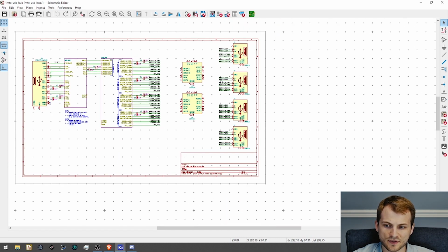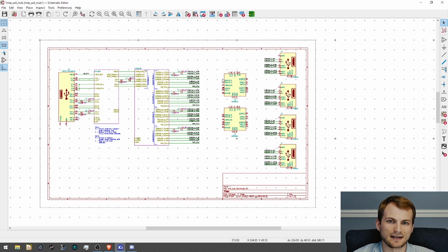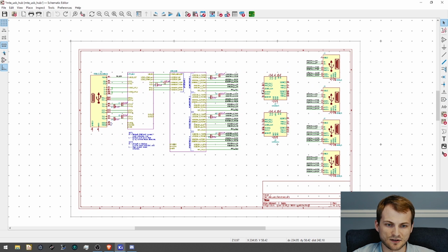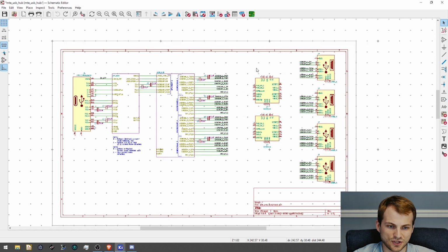And another thing that I think is really, really important with hierarchical sheets is you should never have a connector buried within a hierarchical sheet, because that goes against exactly what I'm saying when I do these. My goal is for it to be easy to understand only by looking at the top level. And if you bury a connector in a sheet, you have no idea. So connectors always have to be on the top level. Anything intricate on the inside can go internal to a sheet.